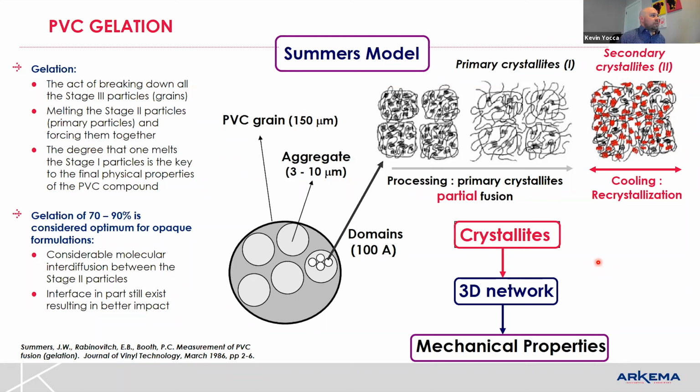So this isn't something, where I've worked with PMMA and polystyrene and other things in the past that are mostly all amorphous. You actually can take advantage of this limited amount of structure that's built in from the chemistry and the reason why PVC wants to have this other secondary bonding that's very strong, and build a structure within the PVC that gives you the final mechanical properties that enhance whatever the properties are you're looking for in the application.